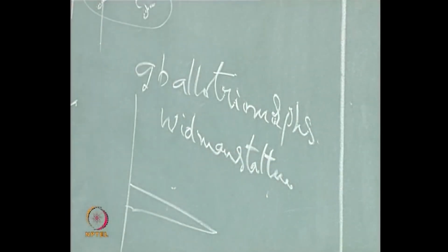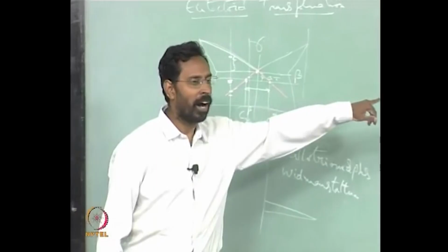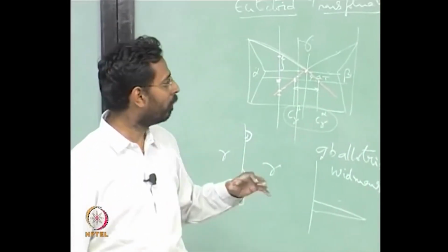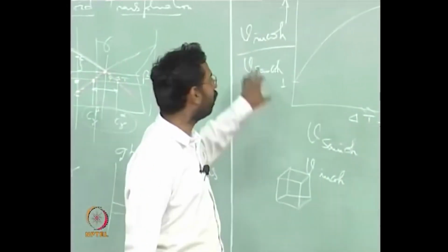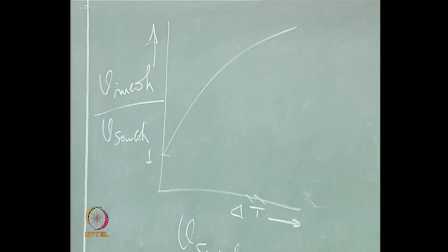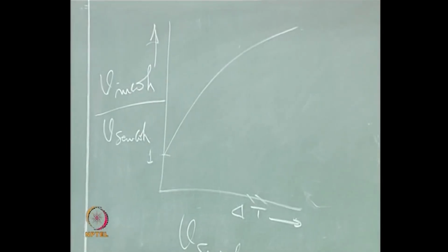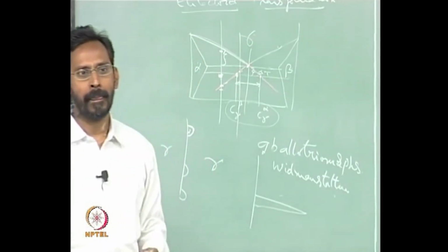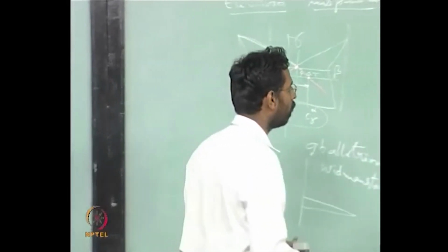Okay. So this is how you would see different types of alpha coming out of the gamma, just because of the growth rates being different at different temperatures, because of the necessity for a semi-coherent interface to maintain the coherency. An incoherent interface need not maintain coherency, so as a result it can grow faster. So why is it incoherent in this case and semi-coherent in this case? That is what I am saying.